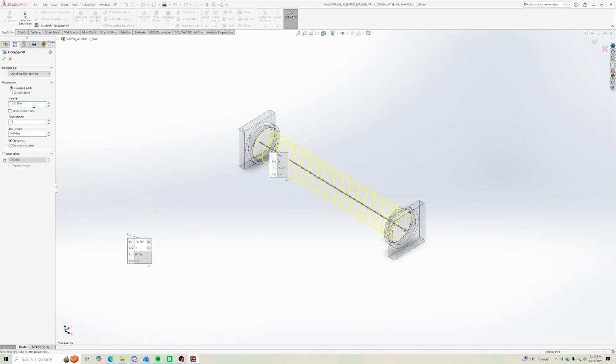Length and dimension to change it, and you also need to change the pitch, which is from here to here that you'll see in the book. Length between two springs. So what I did is go here, and then we'll go to height and pitch. And now you're seeing right here that 0.75 in the book. 0.7465 is just rounding up. And it wants you to change this right here to 6.75 and change the pitch from 0.75 to 0.375.